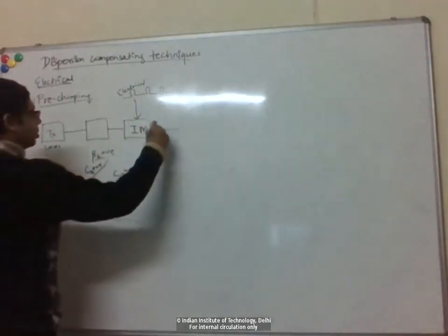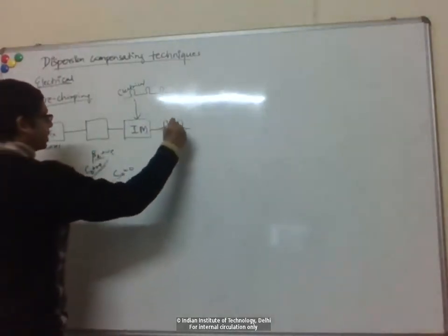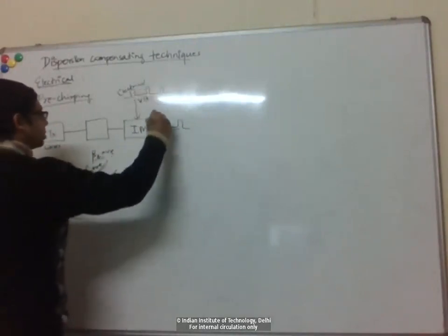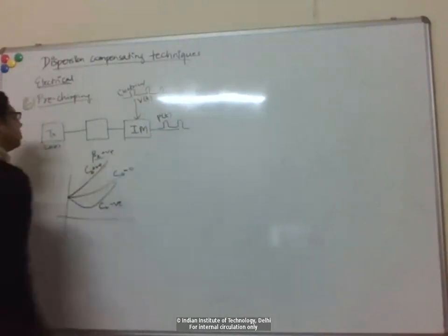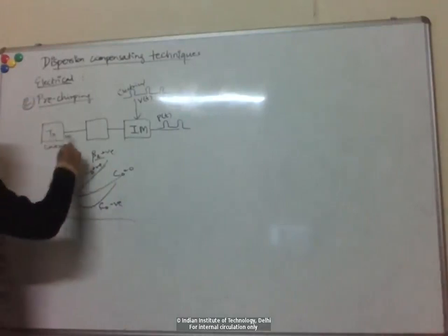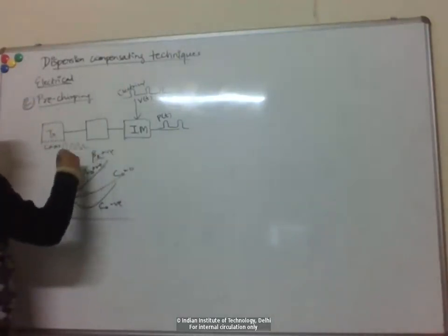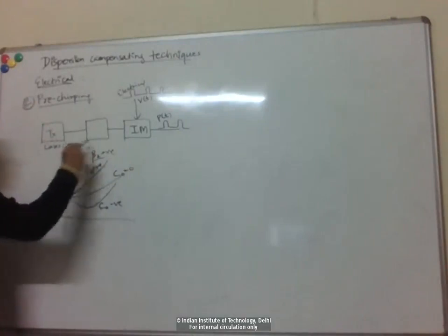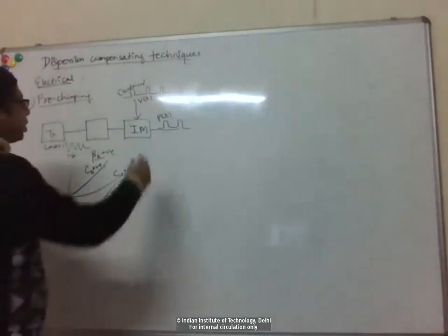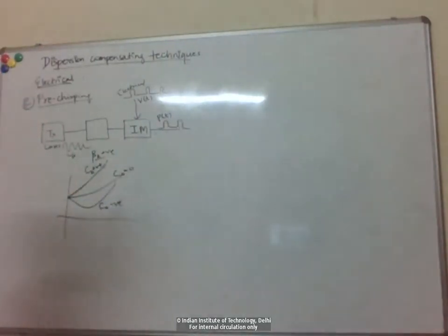So that now the optical pulse's intensity is also modulated like your electrical pulse train, right? So this is optical power now. If you directly send the laser output, which is just a sine wave at omega naught, to the intensity modulator and send it forward, then you get what are known as unchirped pulses. There is no chirping.